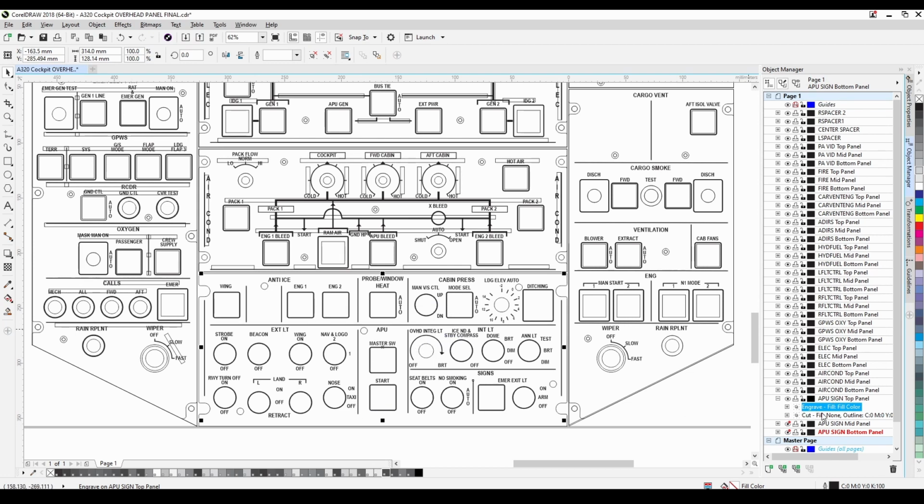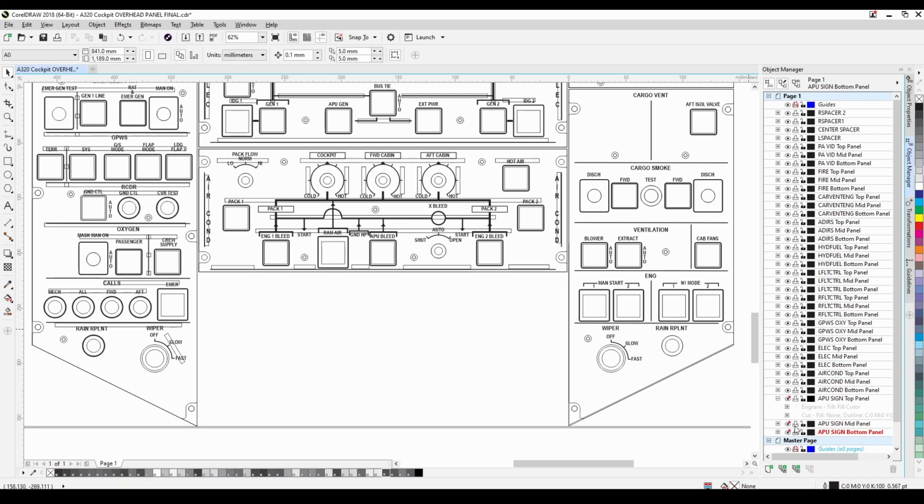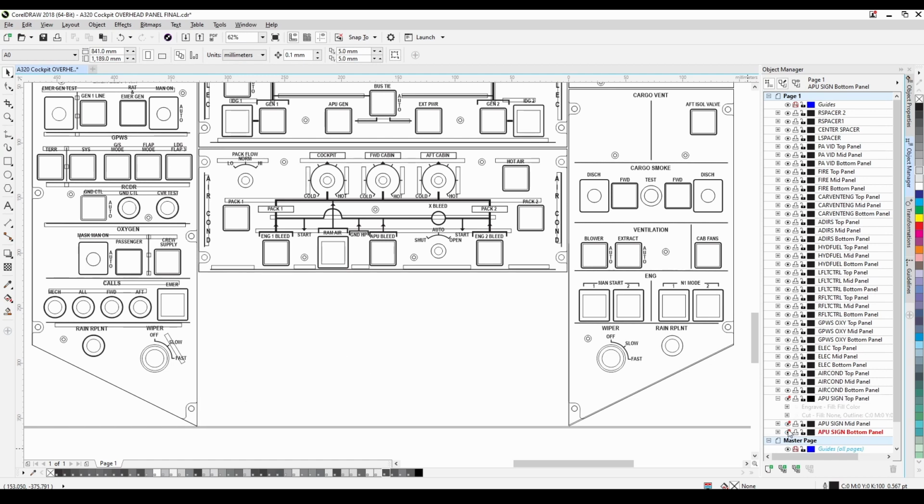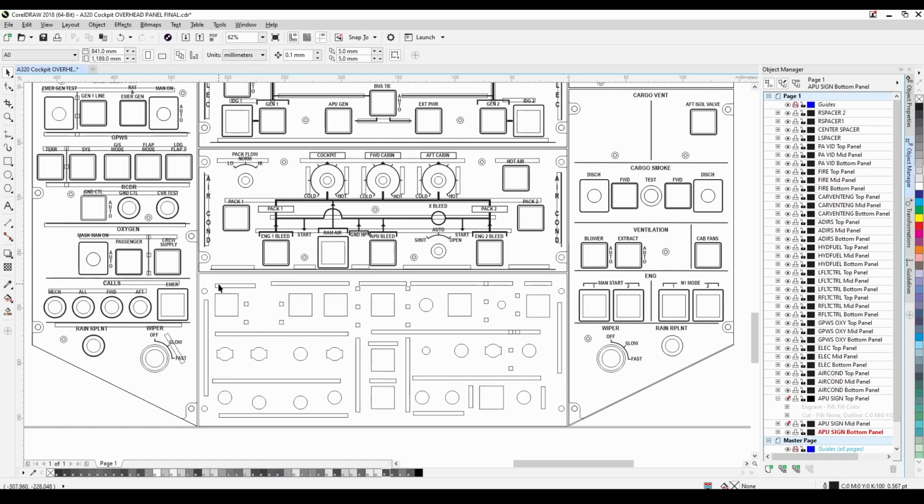So each of the panels has this top panel. If I close the top panel and open the middle panel, it will just show the holes, because it's just for the cutout of the switch. It's just to strengthen the upper panel. So this is 2 mm. The top one uses 2 millimeters opaque white, but the second layer is 2 millimeters clear acrylic. Okay. If we show the third panel, it is actually using 3 millimeters clear panels, but painted black on the rear side.